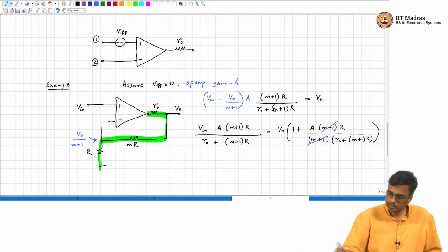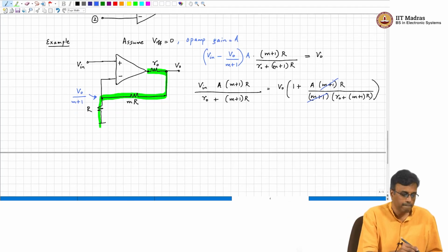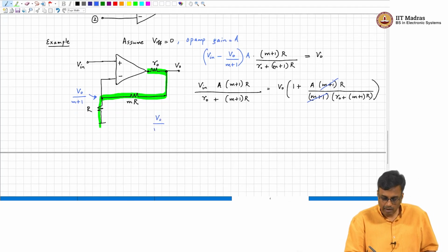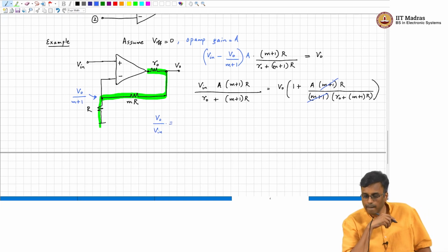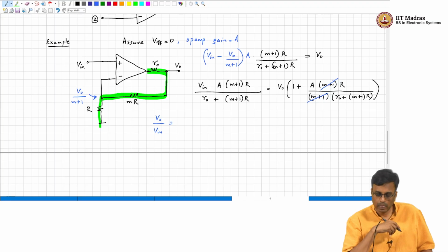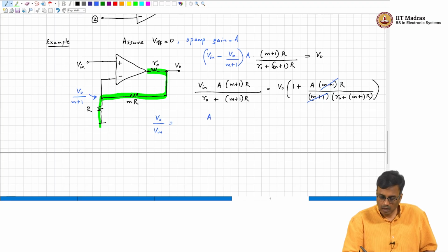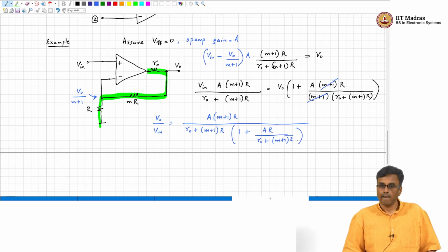So, what do we have? V O by V in is A times m plus 1 R divided by R O plus m plus 1 R, divided by 1 plus A R by R O plus m plus 1 times R. Yes?